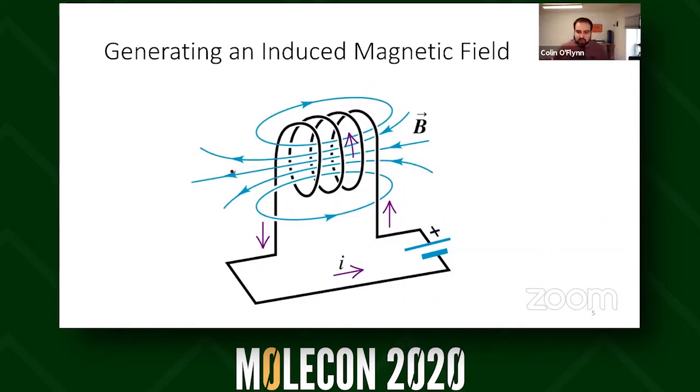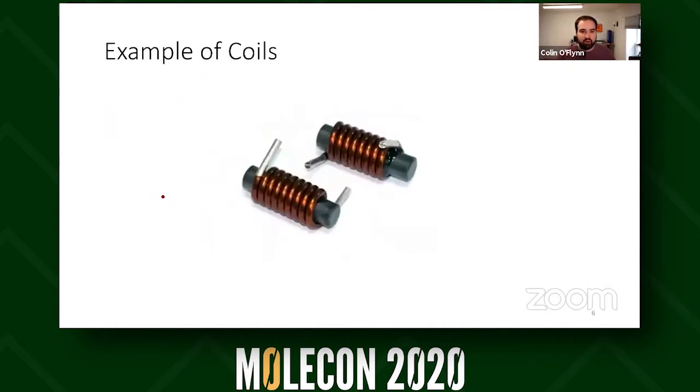And to do this, I'm going to use a strong magnetic field. So we're going to do this with something called electromagnetic fault injection. There's a few ways of injecting faults, and I'll show you a few after this too. But the basic idea of this way is that we have a coil, you pass a strong pulse through the coil, and if I have a target chip here, let's just draw a chip, this magnetic field is going to induce voltages onto the die itself, and these voltages are going to affect nodes and things like that on the chip. So it's a pretty simple idea, but it actually works pretty well in practice, right?